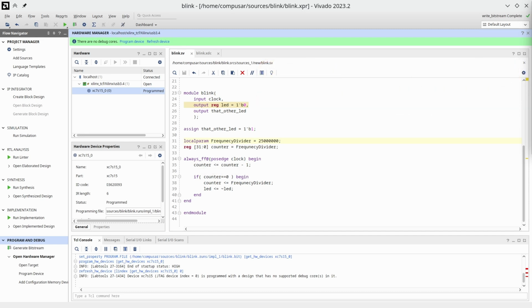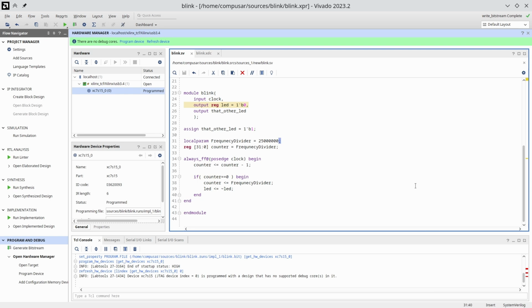Our LED cycle is not at 1 Hz, but at 0.999998 Hz. Granted, at these division levels the difference is not very significant, but your typical divisions will be much smaller, which means the error will be much higher. There are multiple ways to deal with this, but the simplest one is to just compensate for this in advance. If we set the frequency divider accordingly, we can keep the rest of the code as is.